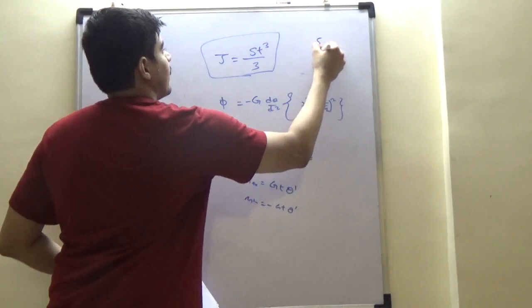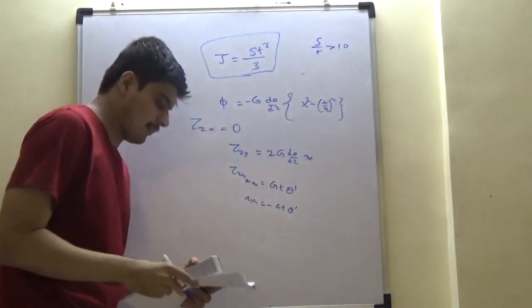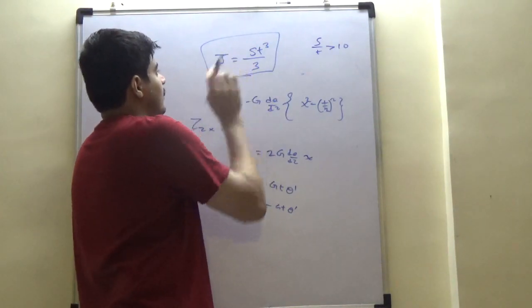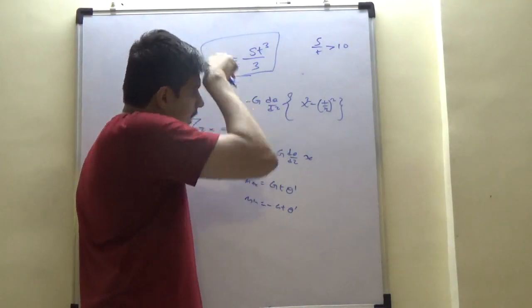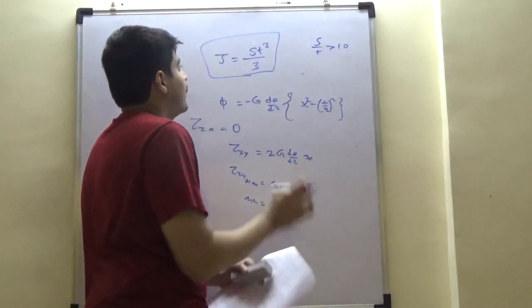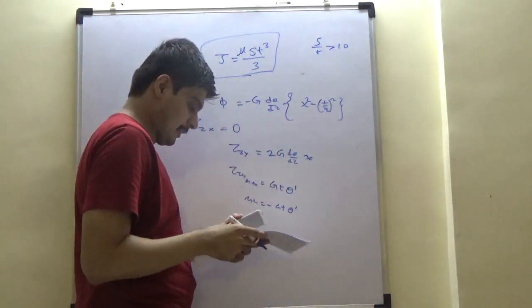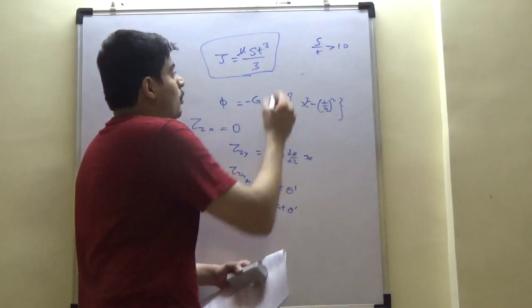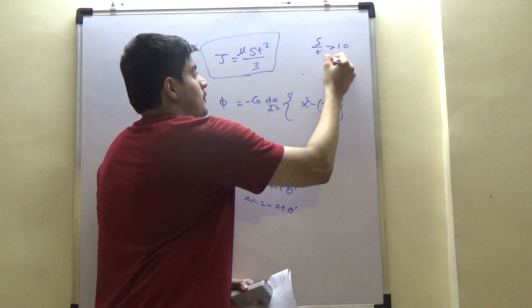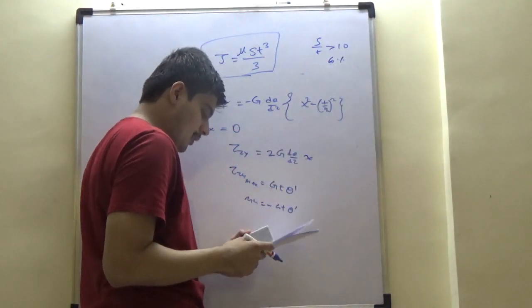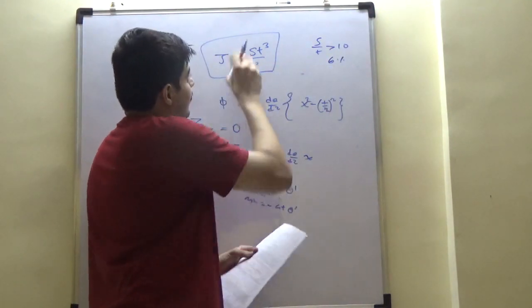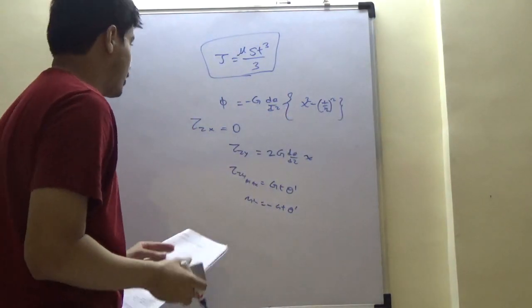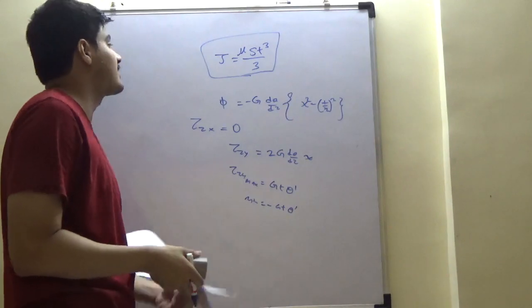And we have said s by t greater than 10, this holds very, very true. In reality, in aerospace, when you start building this first approximation, Prandtl immediately suggested a correction factor mu. Because when the ratios are in excess of 10, error is only about 6%. When they become slightly smaller, they use this. So this is a reference value. So for different s by t, he gave these correction factors for inertia, so that experimental values will start matching.